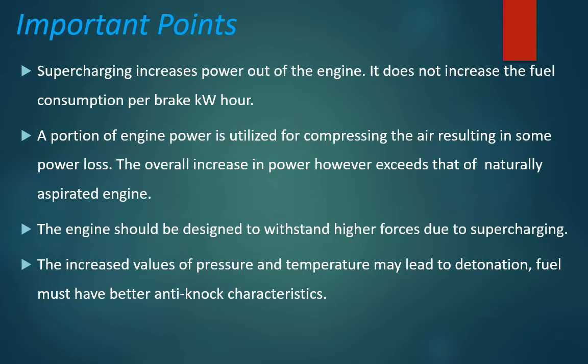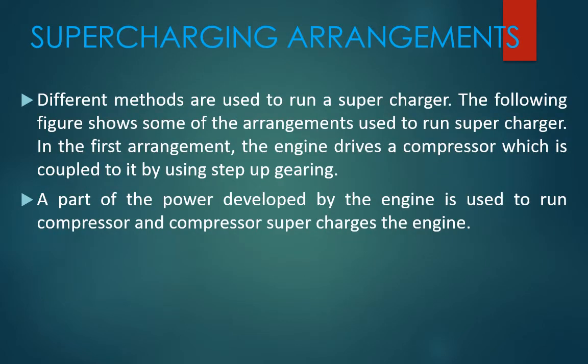So this we will talk about later. The overall increase in the power exceeds that of a naturally aspirated engine. The engine should be designed to withstand higher forces due to supercharging. The increased values of pressure and temperature may lead to detonation. Fuel must have better anti-knock characteristics. So this is the point we are talking about.